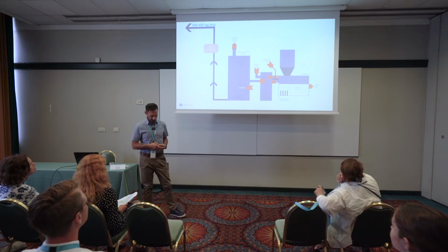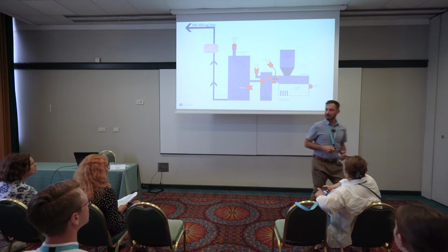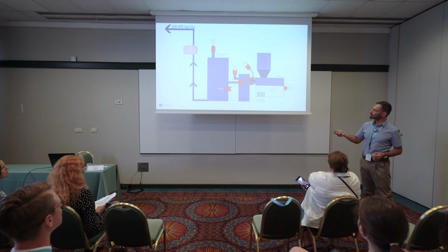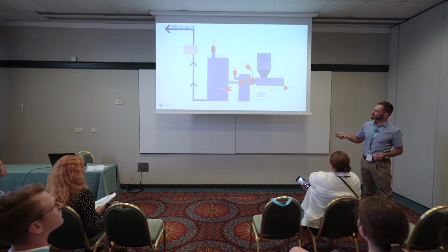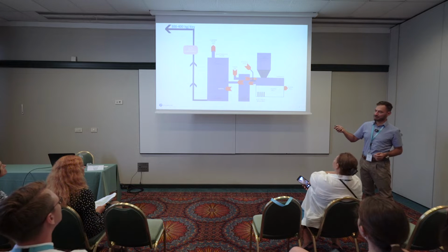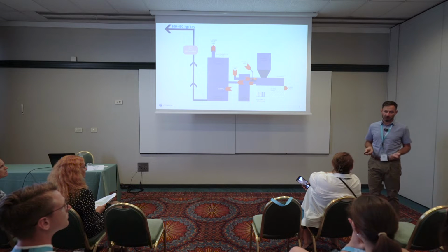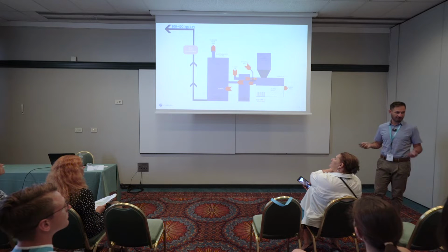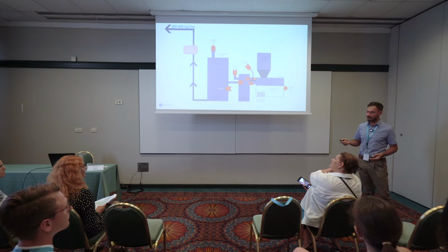This is what a scheme of the process looks like. So we have a glass melt. We are feeding raw materials inside. We are pulling glass out and making bottles. What is left, the flue gases, leave the top of the glass melt and go through a heat exchanger, then to an electrostatic filter, and here we have filter dust that needs to be disposed of. Typically 300 to 400 kilograms of such dust is collected, and this dust is harmful.